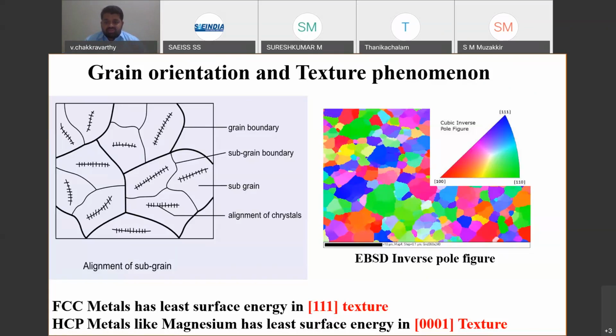Okay, as compared to the 100 direction, if the grains were grown in it. Just imagine 100 means this direction, and triple one means this perpendicular direction, and 110 means this right side direction. So if there are three different directions, the direction which is more perpendicular, the triple one direction, which was represented with the blue color, that particular material will have the highest corrosion resistance.